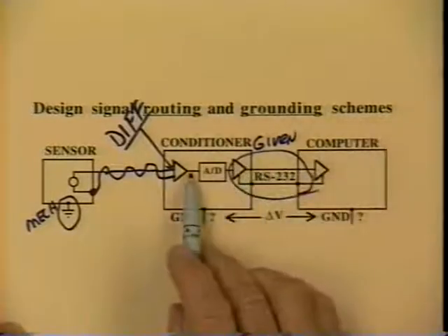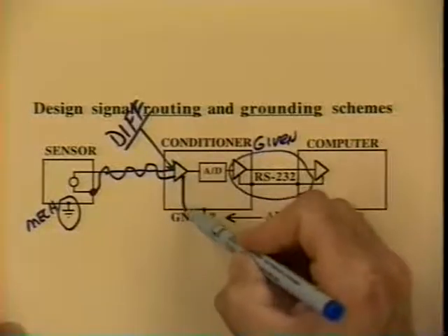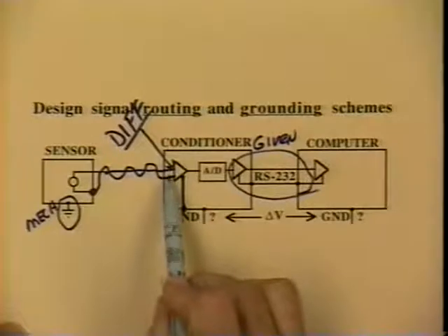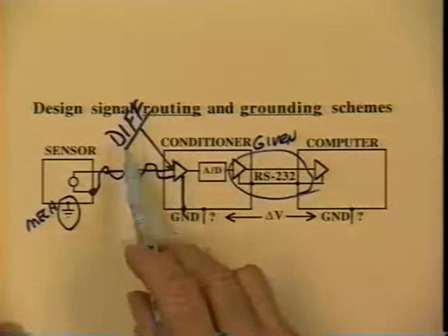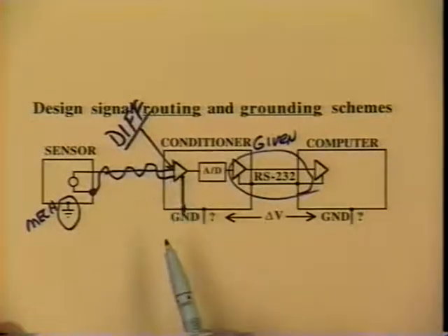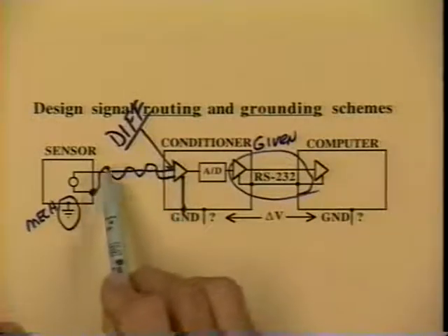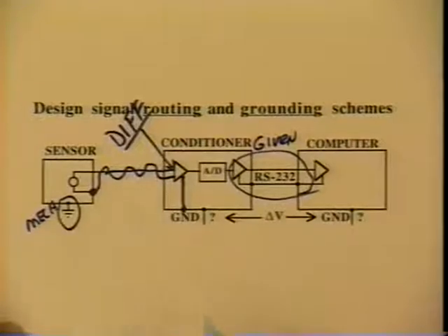Now this is kind of a one-line diagram, at least through here. The output of this amplifier may be tied to chassis. But what I don't want is either one of the inputs tied to chassis. So that's what the differential receiver is going to gain for me. It's going to gain isolation of the inputs from the chassis, so I can be sure that the signal current has to stay on the twisted pair. It's a low-frequency current. If I gave it access to the grounding system, it unfortunately would use the grounding system.